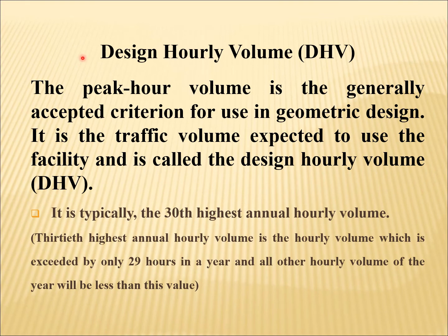Now, look at design hourly volume, DHV. The peak hour volume is the generally accepted criterion for use in geometric design. It is the traffic volume expected to use the facility and is called the design hourly volume, DHV. It is typically the 30th highest annual hourly volume.